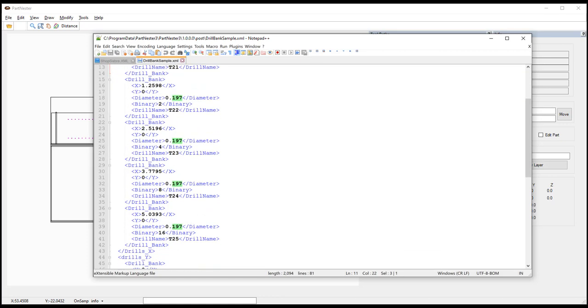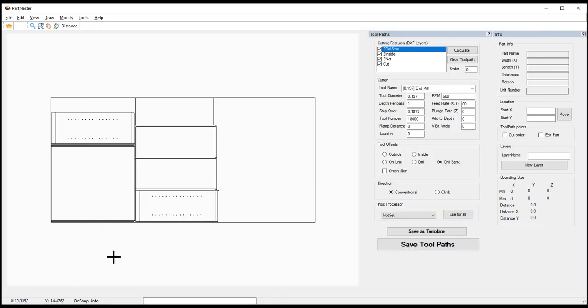So most machines would be set up to have whatever primary orientation your grain is. So in the case of we have this nesting here is in the X direction. Typically all 5 drill bits in the X direction will be set to 5mm.